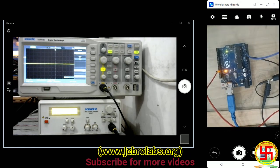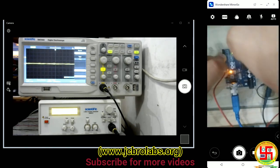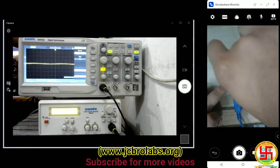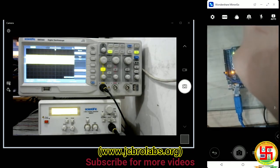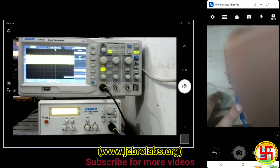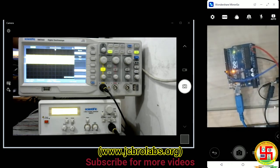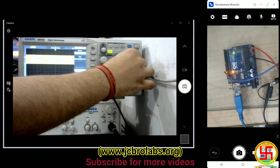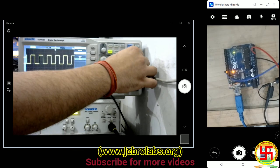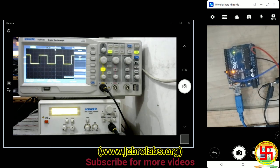So, oops, it may be possible that I have, 8, 9, 10, 11, 12, 13. Yeah, now I changed the connection, so I wrongly connected. Okay, so this red one is from the function generator, and then this blue one is to the DSO. So on the DSO we are getting this waveform. If I expand it, you will get a nice square wave, because it is obvious this is just pin number 13 getting high and low.